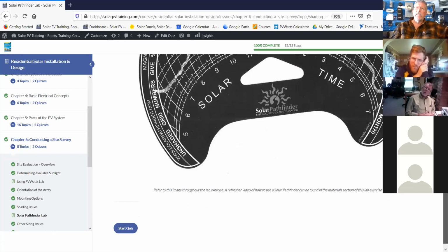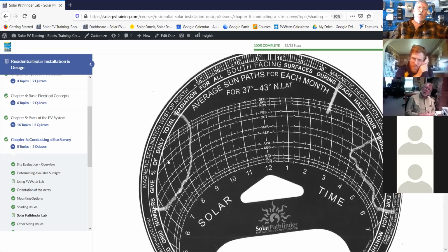Okay, now these little numbers here, like the 1, 2, 5, 6, 7s, what that's telling you is the sunlight that comes during this time of day, like right around noon, is giving it an 8 or a 7 rating. It's more valuable to you than the sunlight that comes in the early morning, where it has a 1 or a 2, because in the morning, there's not as much energy in the sunlight. It's coming in at an angle. So if you add up these numbers all the way across, it should add up to 100%.